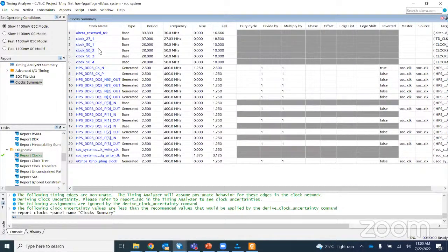Here you can see what the clocks and base clocks are. And these are the clocks which are required on the hard processor system side, which is on the DDR, which is the high frequency design, right? Wherever you want to use it on the SoC side, we can use that DDR3. And you can see the entire clock summary. You can easily understand from yesterday's discussion that we had only one clock, but now you can see how many clocks there are, which are the base clocks, and the clocks showing as generated are the clocks which are generated from the base clocks.